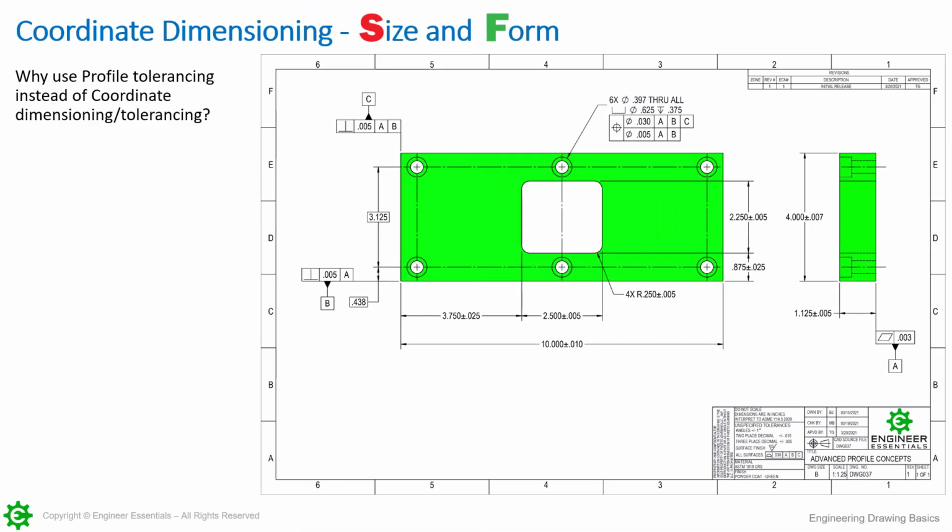First up here is the size. On that GD&T basics framework with size, location, orientation, and form, the reason why that's so important is that's how we dimension prints. That's how we know that we have obtained our goal for creating that drawing. Every feature of size must meet all of SLOF.